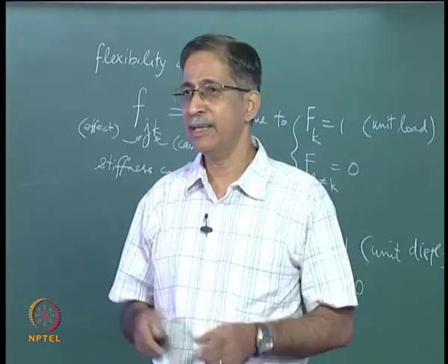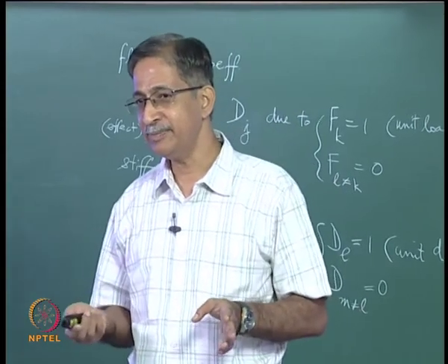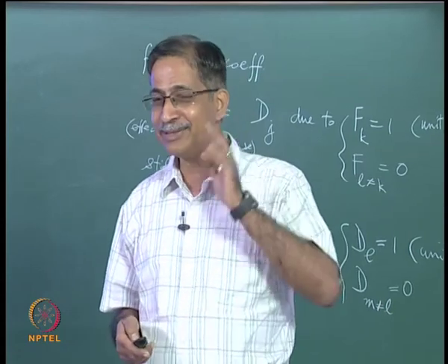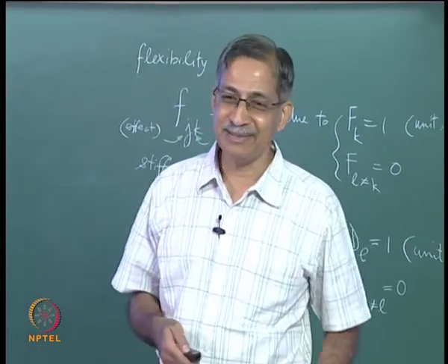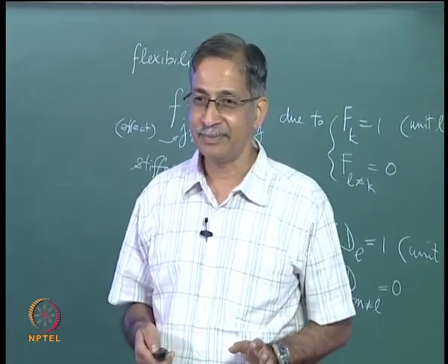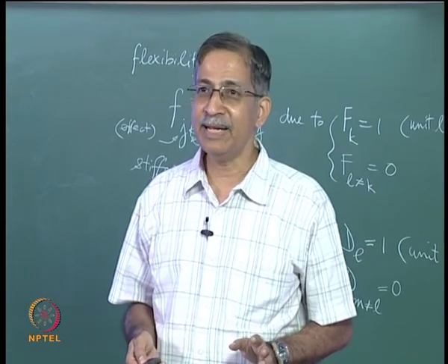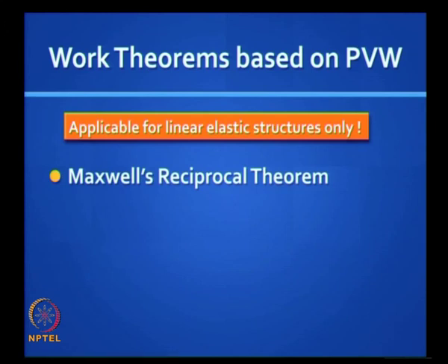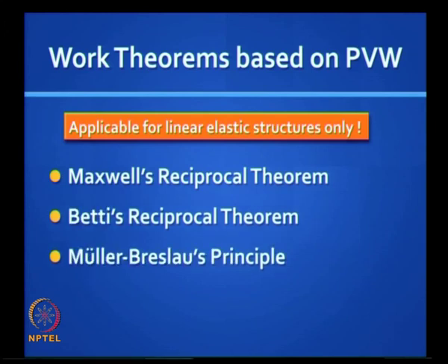Some work theorem. Can you just name the work theorems? There are 3 work theorems. Castigliano's theorem belongs to energy methods, work theorems. 3 of them, they are applicable to linear elastic structures. There is Maxwell's reciprocal theorem, then Betti's theorem, and Müller-Breslau's principle. We will see this in the next class.